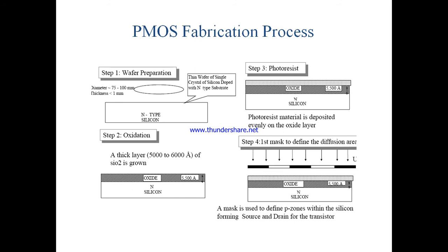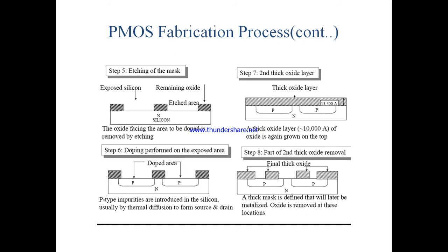And next step is the remaining photoresist is removed and a thin layer of silicon dioxide SiO2, approximately 0.1 micrometer, is grown over the entire chip surface. Then polysilicon is deposited on top of this to form the gate structure. In the fabrication of the fine patterning device, precise control of thickness, impurity concentration and resistivity are necessary.